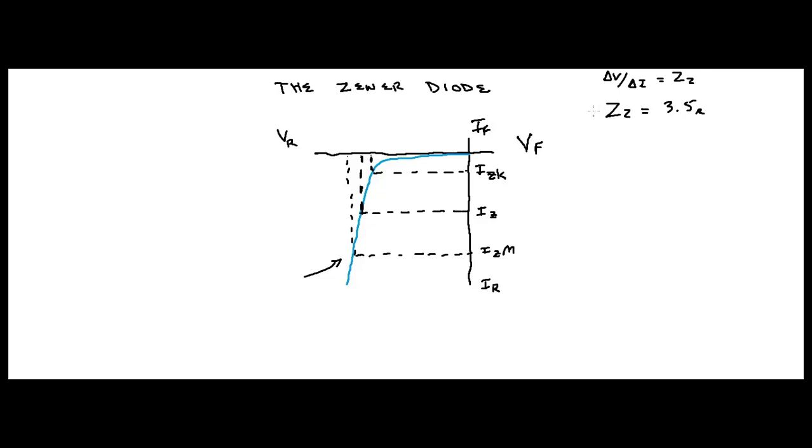And the problem gives you that. You can get that from the data sheet of a Zener, so this is a good parameter. They measure that for you. They're also going to give you VZ, and for this problem, let's say VZ, which is right here, is 6.8 volts. Its associated IZ is 37 milliamps, and that pertains right here. So you have ZZ and you have VZ.